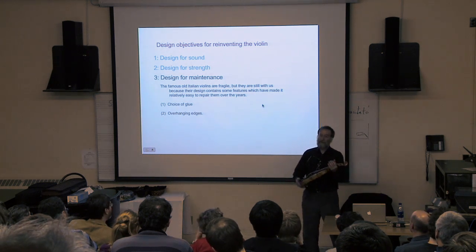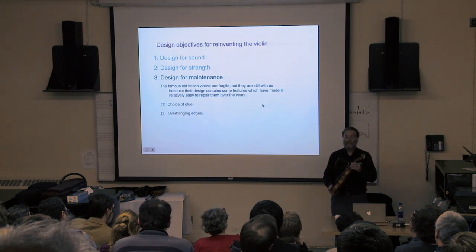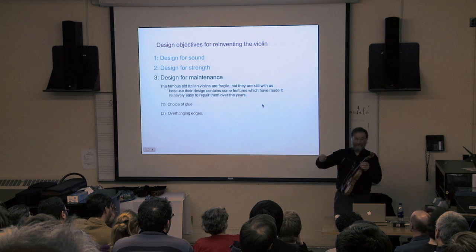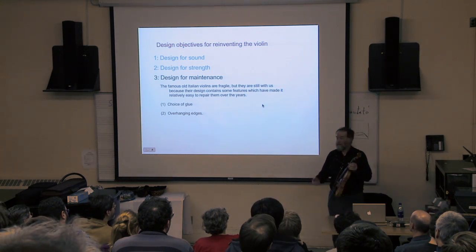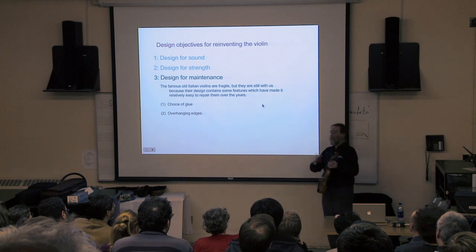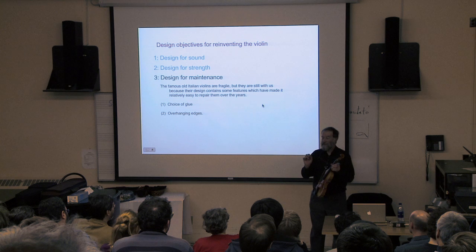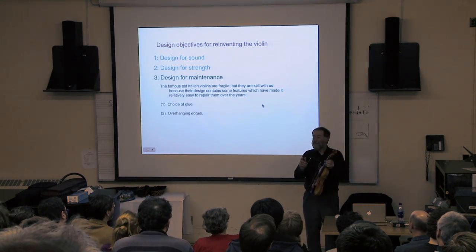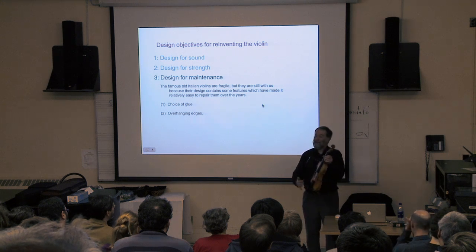First of all, we've got to glue the box together. Now if we use glue which is too strong, then when you're trying to open the box up you don't go through the glue, the chunks of the wood fall out, so then you've got a major repair job on your hands. You use glue that's too weak and it falls apart of its own accord. Glue that's just right is just a bit less strong than the wood, so that you can open the join carefully, but so that nearly all the damage is confined to the layer of glue.